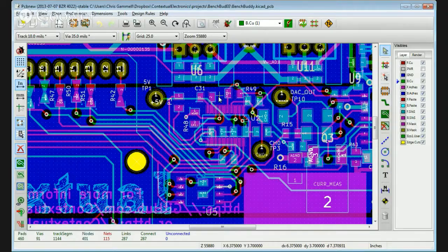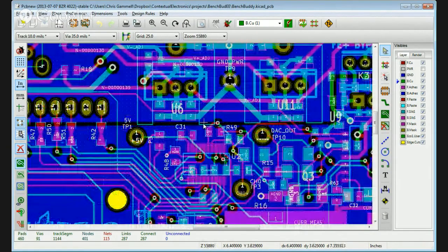Okay, I think that might be something that didn't get back annotated into the schematic. Like the actual part number? Yeah, the actual part number. Ferrite bead. Usually, it probably was a bad idea to call that L. Usually you'll see that on schematics as FB for ferrite bead. It'll still be drawn as an inductor, but usually the prefix for the reference designator will be FB or similar. And usually for analog to digital converters, I put those on the analog rails as well. You'll see that pretty commonly.